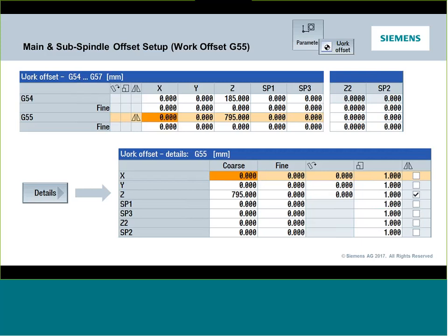Now, a good question came in from Jay. Does the Z direction affect the turning direction of the spindle? No, it should not. It should only have an effect on the physical linear motion of the Z axis.